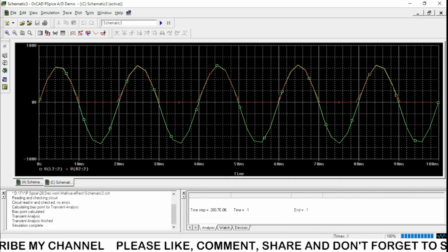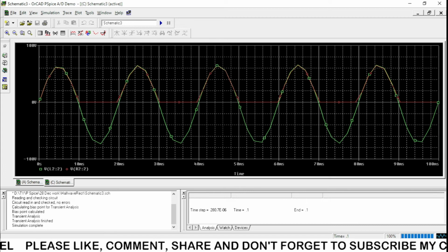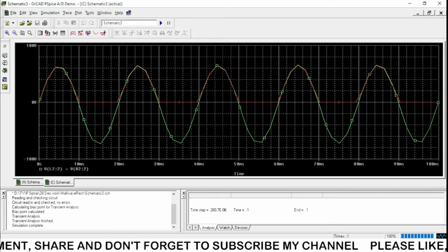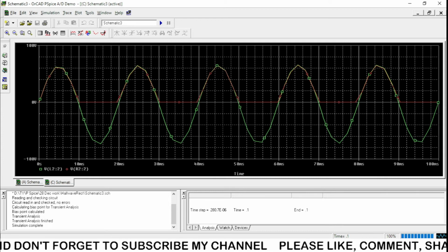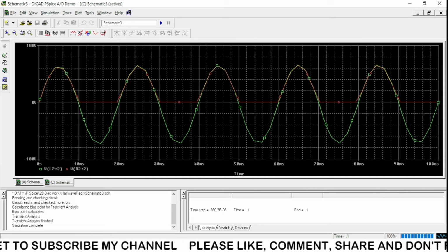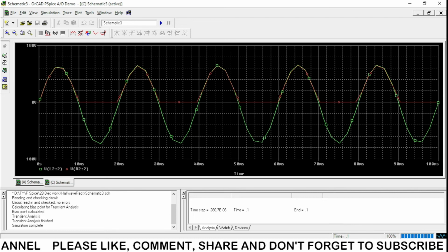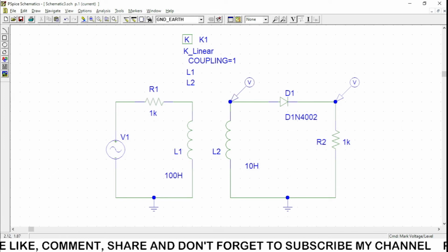Now the red indicates the half wave rectification. The half wave is rectified. At the next half cycle, meaning the negative half cycle, it remains like 0. Then again for the positive half cycle, the red indicates that it is in the positive direction. The positive cycle appears as it is, the negative cycle is clipped, so we can say it is rectified actually, and we are getting a pulsating DC. So how to remove the pulsating DC? I have said that we are going to use a filter here. So how to use a filter here?